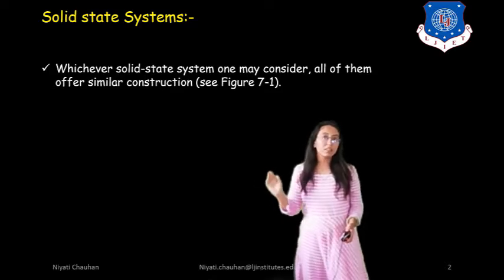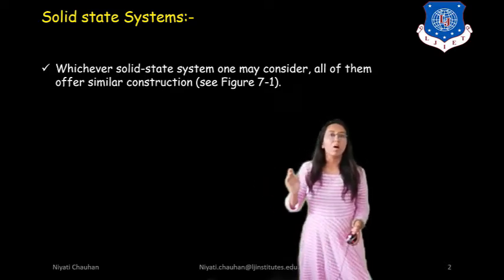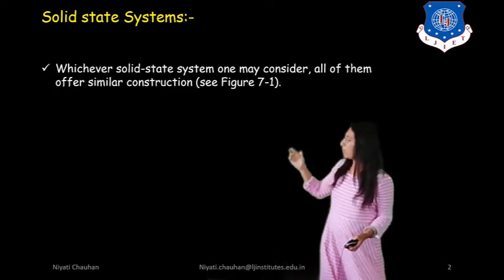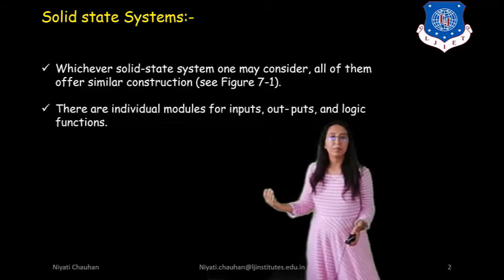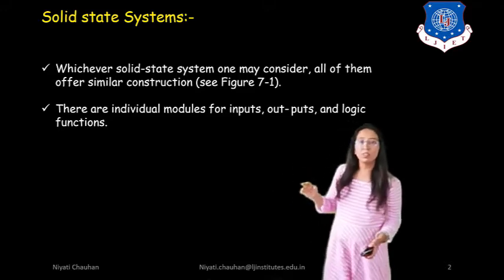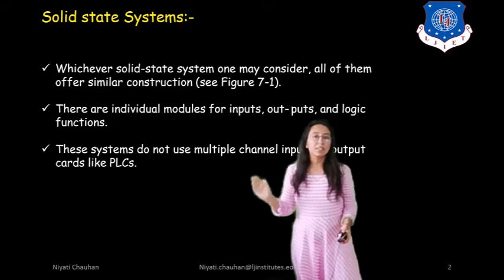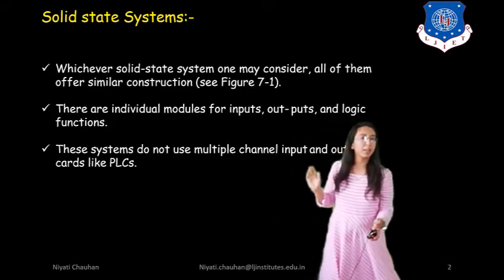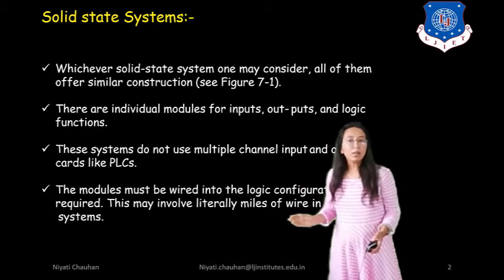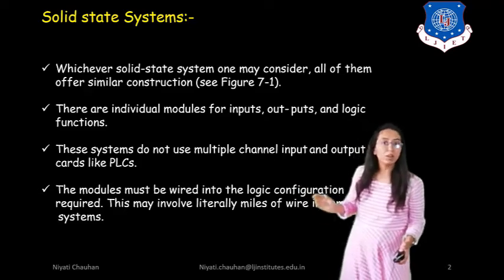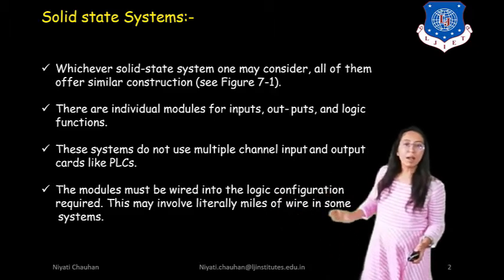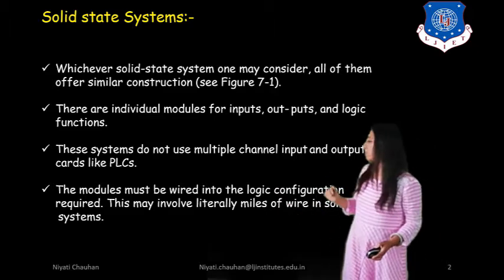Whichever solid state system one may consider, all of them offer similar construction, and we will discuss this figure in the next slide. There are individual modules for inputs, outputs and logic functions. These systems do not use multiple channel input-output cards like PLC. The modules must be wired into the logic configuration required. This may involve literally miles of wire in some systems.